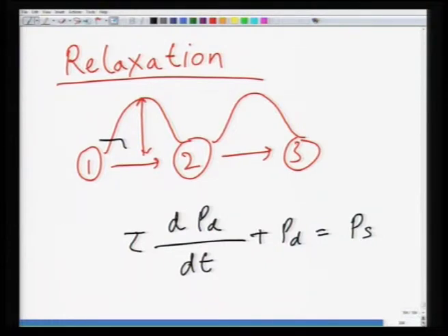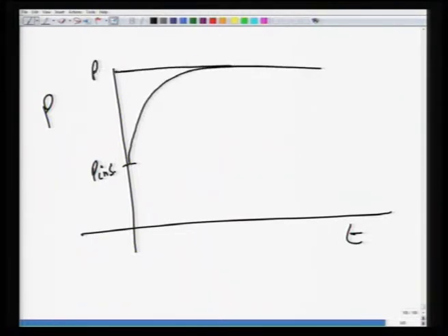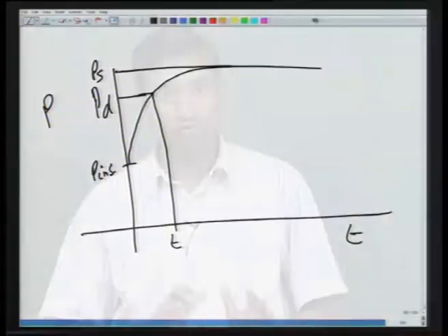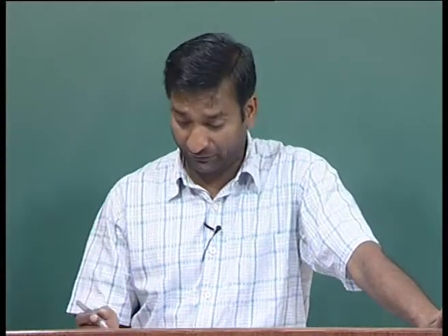If you make a plot of polarization versus time, you have an instantaneous polarization. So, this is P instantaneous, and this develops into P_s in a time dependent fashion. This is the saturation polarization, and polarization at any given point of time between these two stages is time dependent polarization. This is because of the need of the molecules or the groups of atoms to move from one position to another in a time dependent fashion, because they are heavier groups.